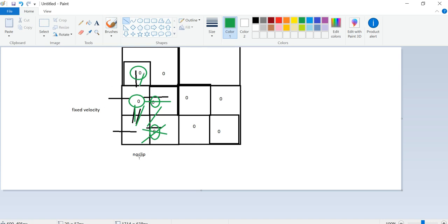So to prevent this confusion from happening, and to prevent OpenFOAM from trying to guess what all these values are instead of zeros, you need some kind of initial guess. Let's give OpenFOAM a little bit of a helping hand in that sense. Maybe here the velocity, we will expect it to be 1. Here the velocity is a bit faster, we expect it to be 3. We could actually manually input all of these, but that would be very troublesome. So instead, what we want to do is some initial guessing first.